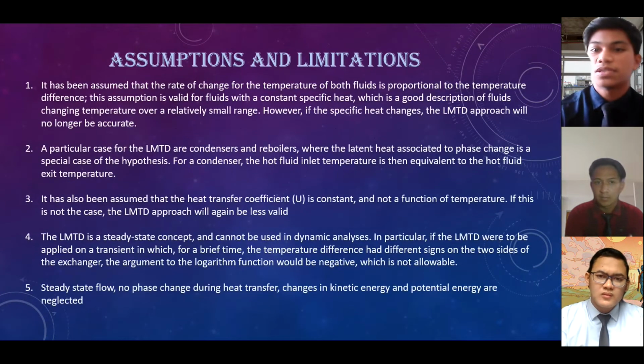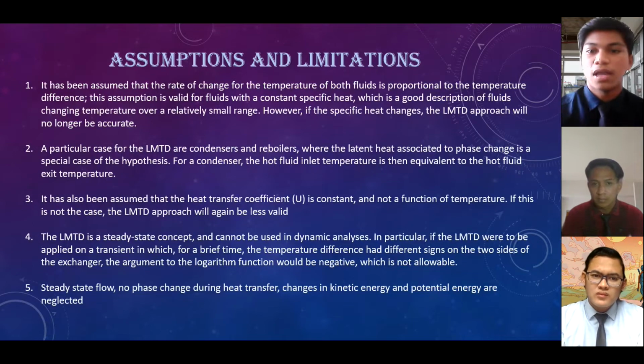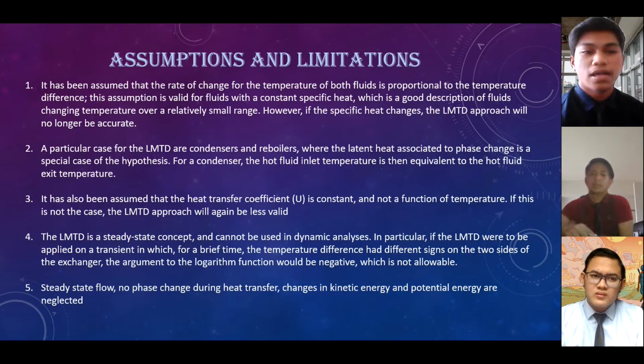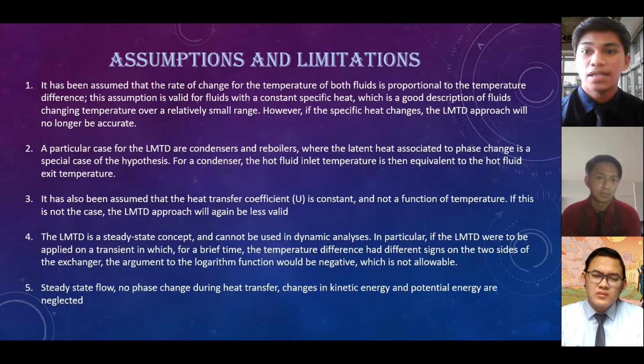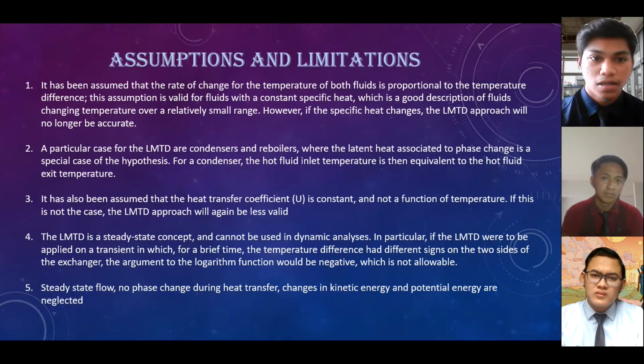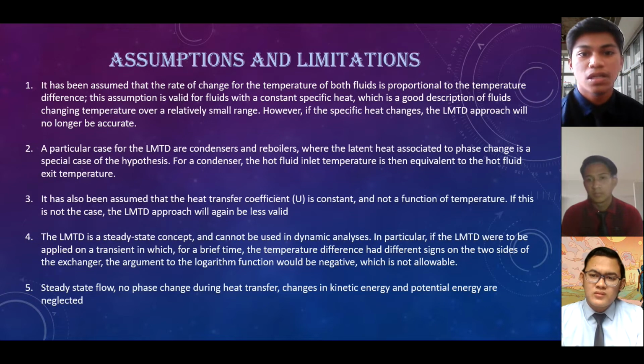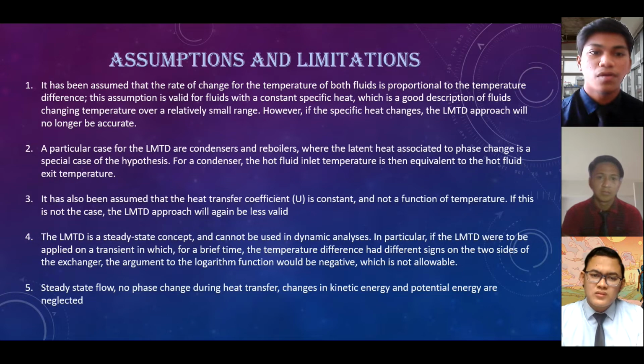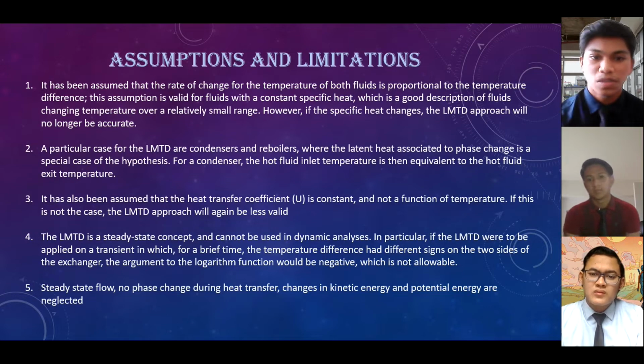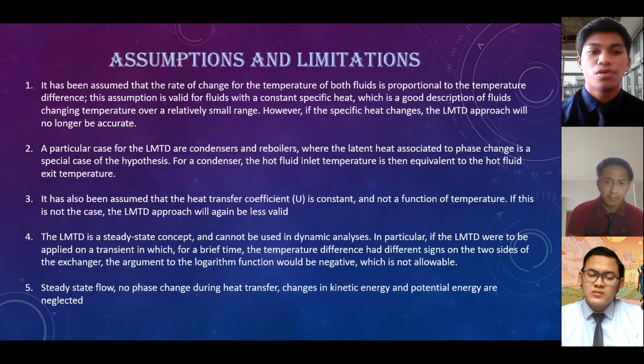So these are the assumptions and limitations for LMTD. It has been assumed that the rate of change of the temperature of both fluids is proportional to the temperature difference. This assumption is valid for fluids with a constant specific heat, which is a good description of fluids changing temperature over a relatively small range.